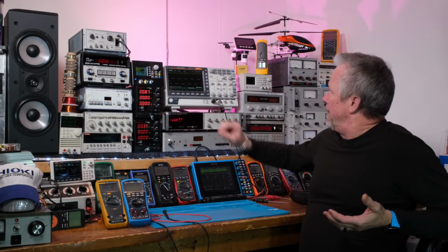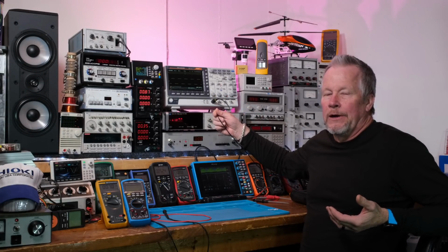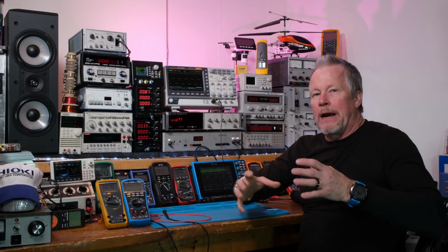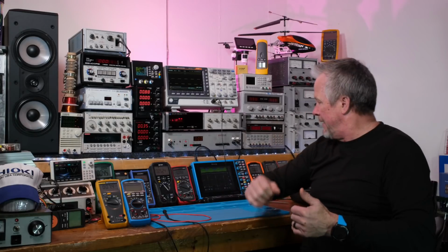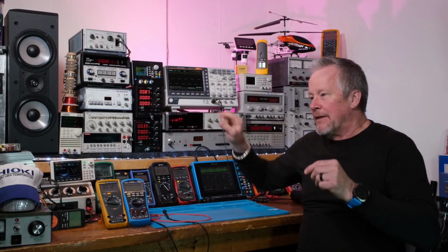The reason people do is if they're looking at an AC circuit where they're on the primary side of the power, which we'll talk about, primary and secondary side, but if you're on the primary side, meaning where the power comes in, and you have that little ground strap tied to anything but earth ground or chassis ground, the scope probe is going to short that to whatever you have it tied to.